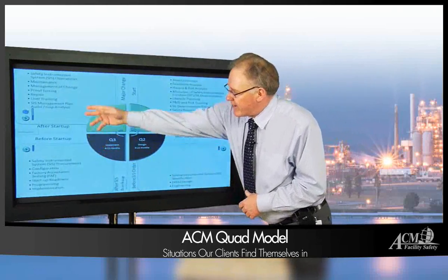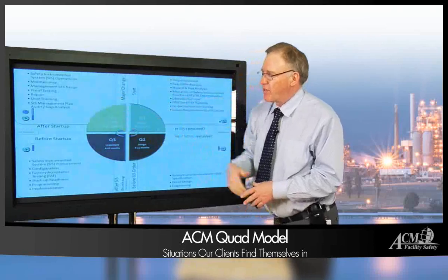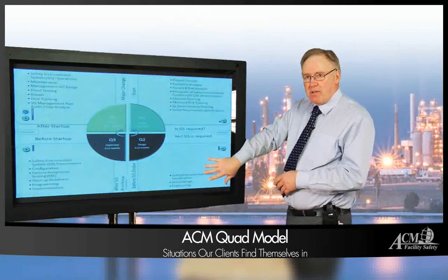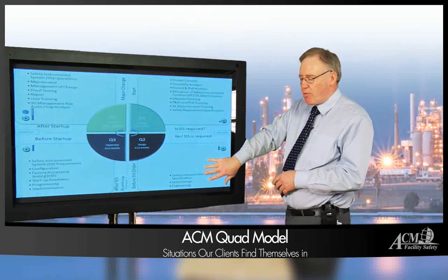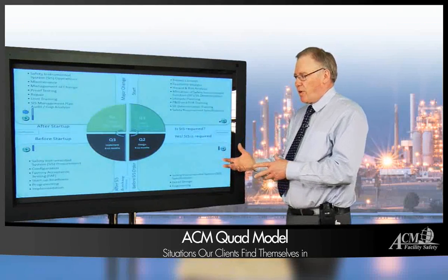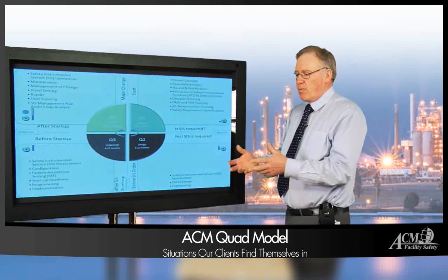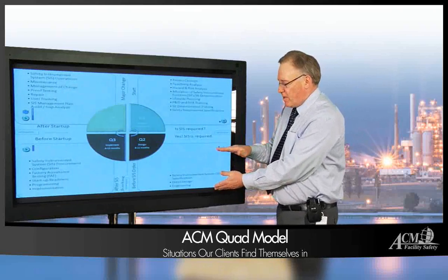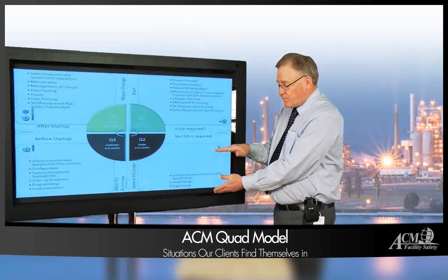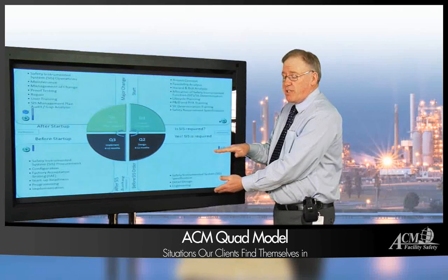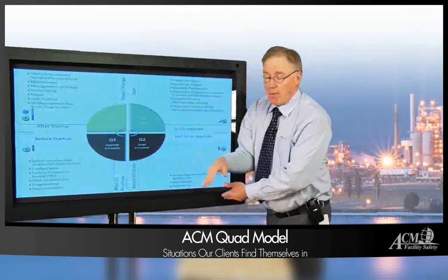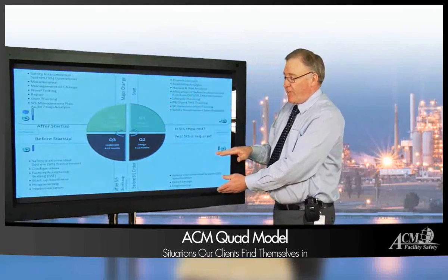So once we get into that, then there's the operations and maintenance side. The operation and maintenance procedures were all designed back here. That's what separates this kind of critical safety system engineering project from a normal control system engineering project: unfortunately, or for the benefit of everyone, you have to figure out what your operations and maintenance procedures are back here in quadrant 2, in the design quadrant. Normally, in a normal control systems project, they'd be done perhaps after you start it up, but in this case, you have to do them here.